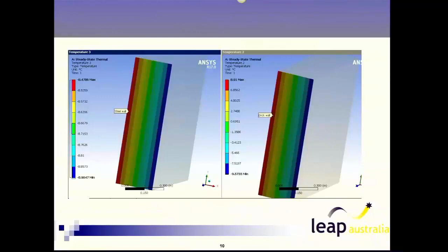Okay, so if we do a simulation of this, I'll show you this model in a few minutes. You can see the temperature gradient across the wall. The colours are the same, but if you look at the temperatures, you can see that this one goes from -8.4 to -8.9, whereas on the brick wall it's +8 to -9. So there's a huge temperature drop across there.